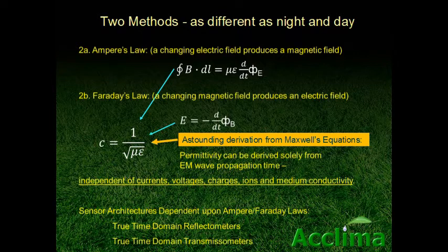There is a precaution here. As EM waves pass through soils, they become attenuated by soil ions and are distorted by complex permittivity components in various soils. If currents, voltages, charges, or fields are used in the time measurement, then Gauss's law taints the measurement and it becomes subject to errors introduced by soil conductivity. In order to avoid the impact of Gauss's law, it becomes necessary to digitize the waveform at very high resolution and then use digital signal processing algorithms to extract the temporal properties of the wave, independent of magnitude.